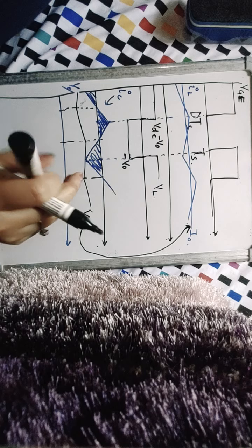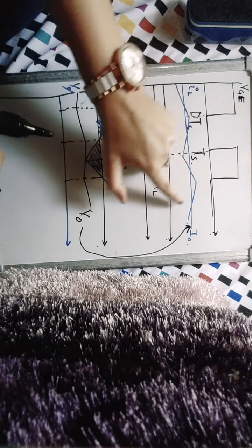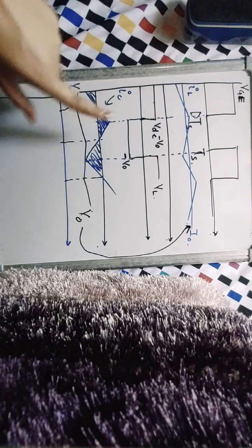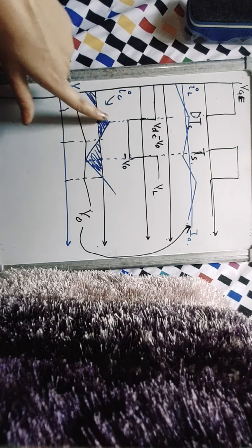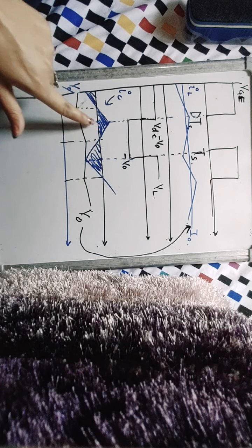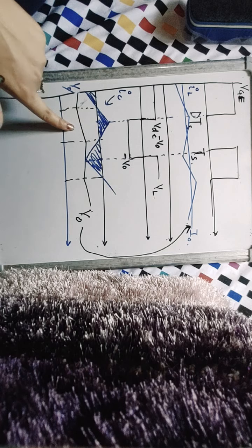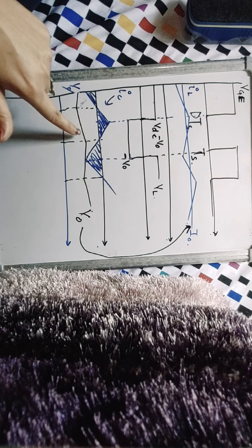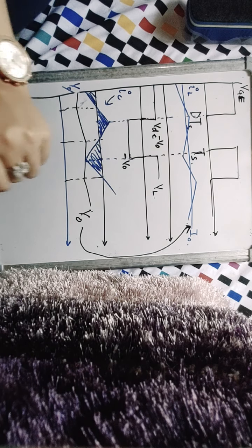But you should know that the design of L will determine the ripple in inductor current, which is in turn the same ripple as that in the capacitor current, and the ripple in this current will in turn dictate the ripple in the load voltage, which means that the inductor as well as the capacitor determine your load voltage ripple. It's a misnomer.